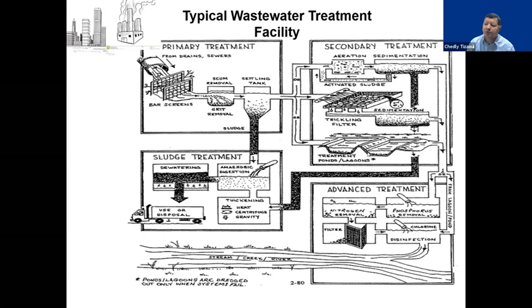And also you could have ponds and lagoons, which is a practiced system as well from antiquity possibly, where you have the wastewater just settling in a lagoon, and you will have microbes there to do the treatment, as well as you have sedimentation in those lagoons. So that's the secondary treatment, and that's the purpose of what we are going to look at today. These processes obviously produce solids, and those solids are called sludge, and that sludge needs to be treated in specific treatment systems before disposal.